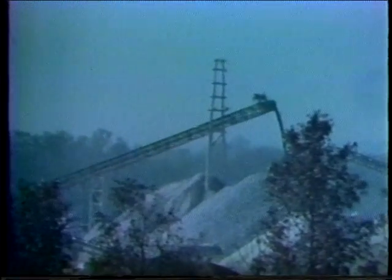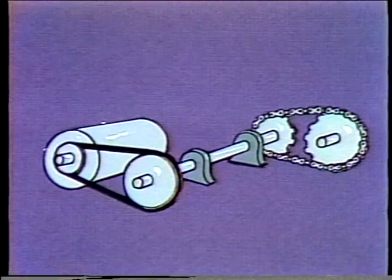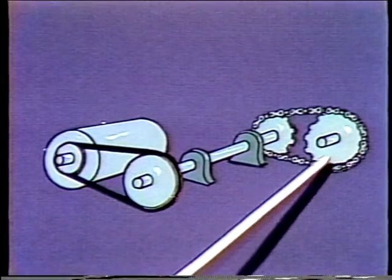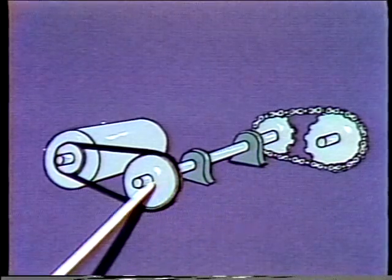The next point to consider is a drive for the conveyor. It's frequently a shaft mount. In this case, a shaft mount reducer is mounted directly onto the head pulley shaft, and this in turn is driven by a V-belt from a motor. The drive may be a direct chain drive from a reducer, or there may be a jack shaft with V-belt and chain drive. A jack shaft is the name given to an intermediate shaft, as you see in this sketch, this one here.